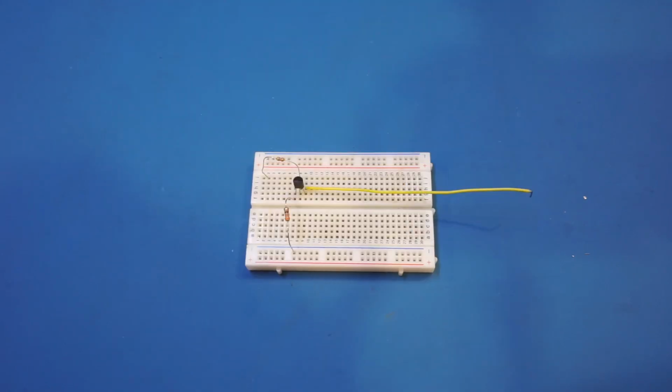components. In the good old days, when choosing the output transistors or MOSFETs for Class B amplifiers, for example, curve tracers were commonly used to ensure that the parameters of these output pairs are closely matched to reduce signal distortions.